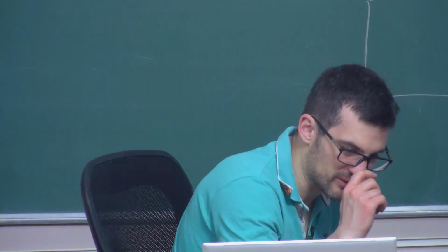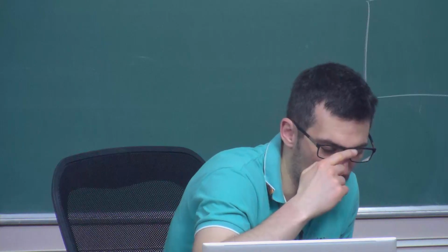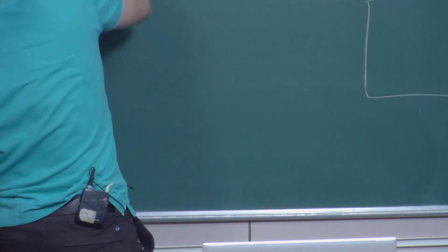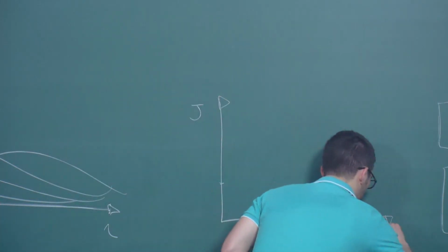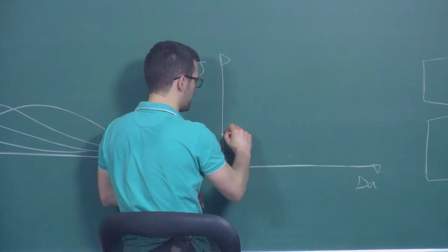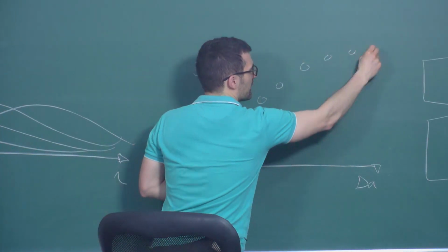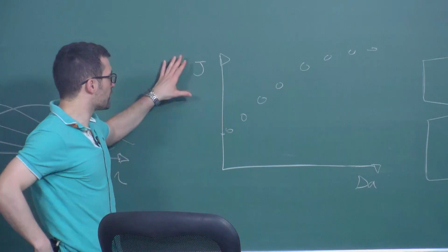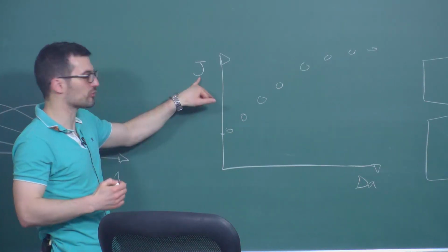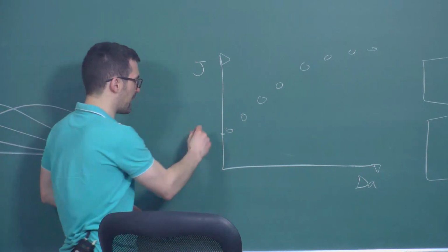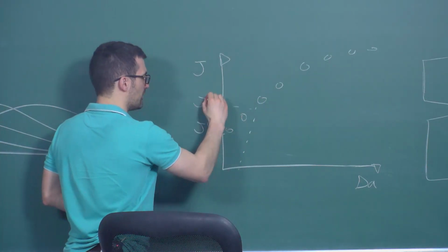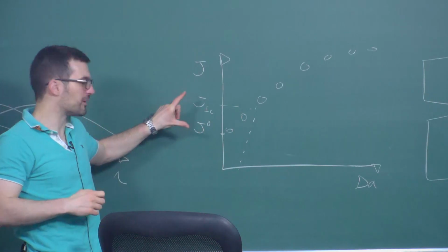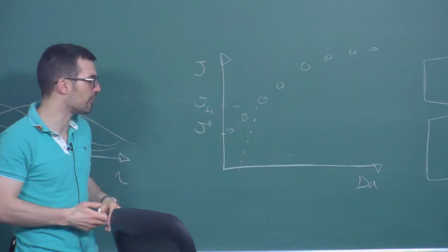Yes, so actually, this is a good question, and I think one of you asked me that in the break. And I remember once I presented this to industry, and they raised exactly the same question. They were very puzzled. If you do a fracture mechanics test, J versus delta A, the experiments will look something like this. Eventually you saturate a little bit, but it looks something like this. So everyone doing experiments always thinks, okay, my fracture toughness is not a constant property. My JC0 it is, and sometimes they define at 0.2 some sort of J1C or JC. Those are constant properties, but if you think of subcritical crack growth, this is something that evolves in time. However,